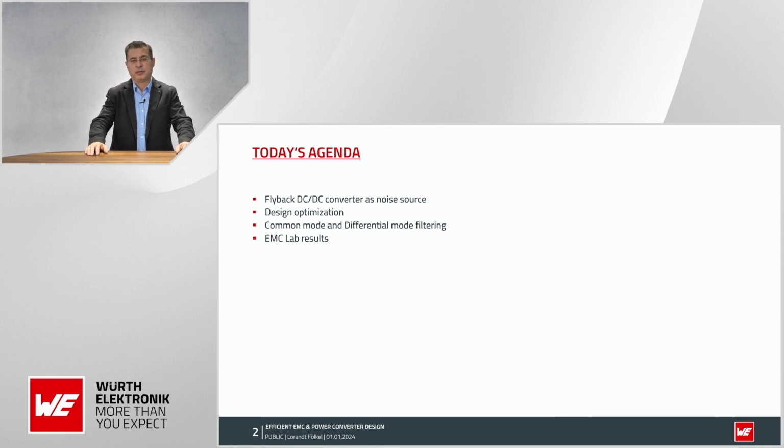We will look at the flyback topology like a noise source and try to make a design optimization, to find out which filter design and which filter step improves your EMI in terms of emission. After that, we will see what the common mode and the differential mode noise are, and then we have the EMC lab results.